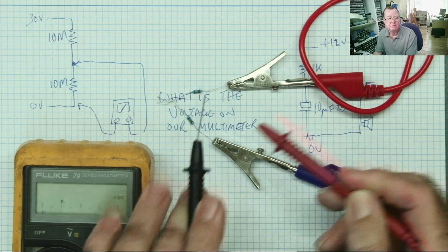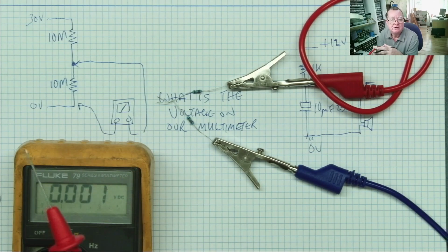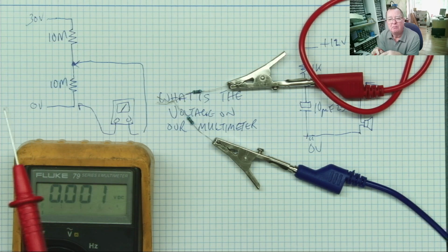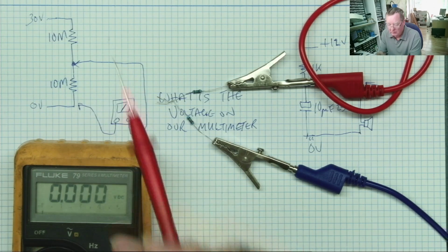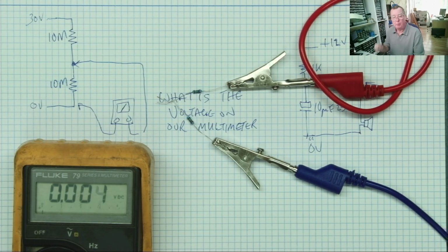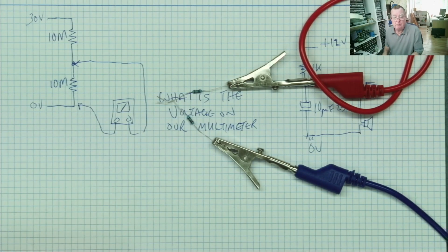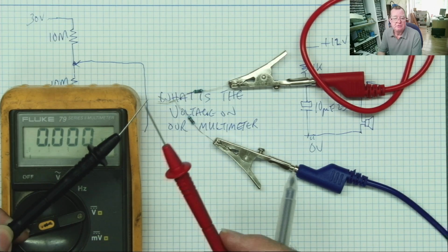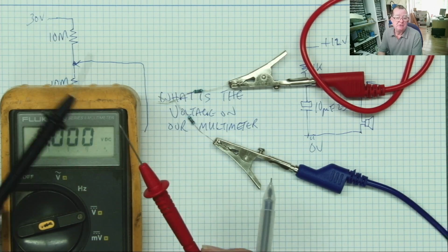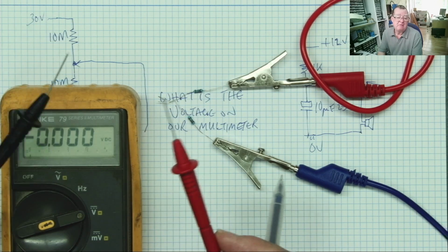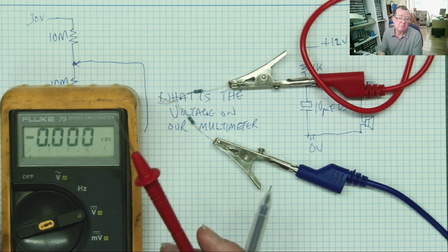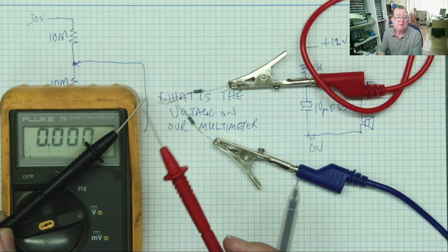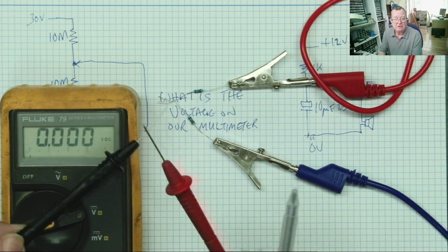No, I've got 10 volts. So I've got 10 volts across each resistor and 10 volts missing. So does that mean Ohm's law is actually not correct at all? Well, it doesn't actually. What is causing this to happen, and I will prove it, is that our multimeter is a resistor. So to measure voltage, some current has to pass into the multimeter, yeah? And it's a very high resistance. It's actually 10 mega ohms.